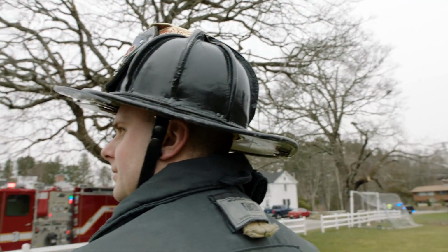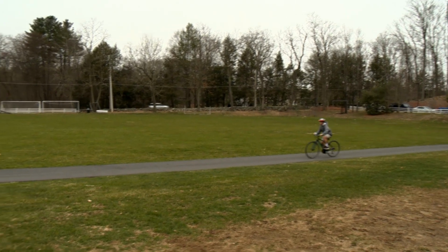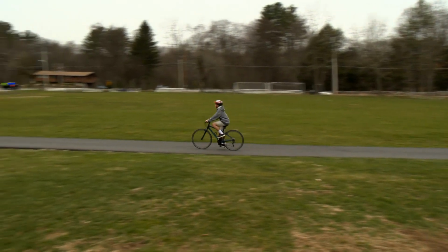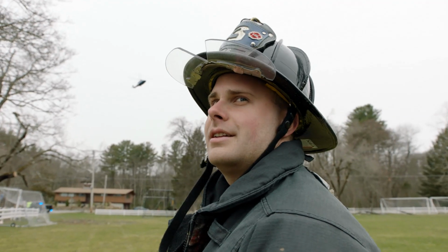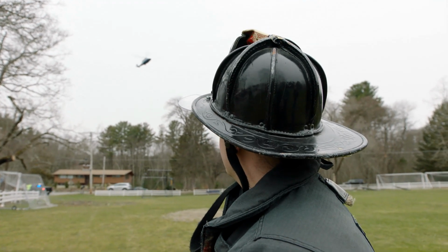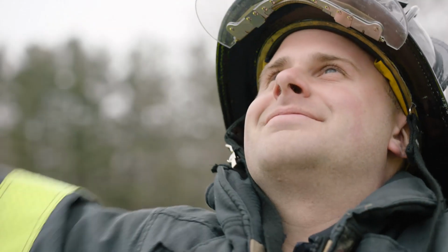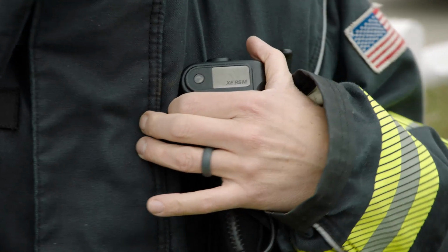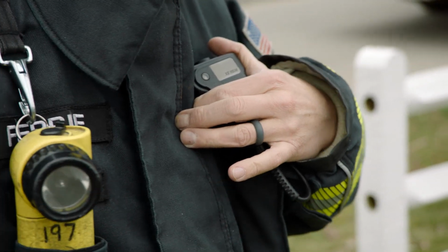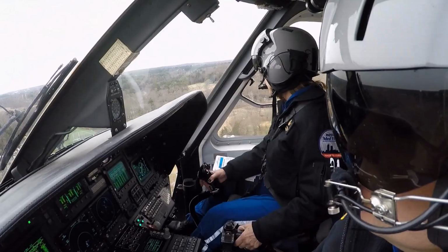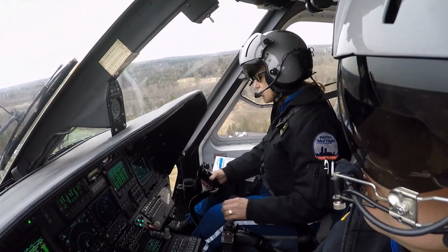If the LZ command sees a hazard in the LZ area, such as a person running or a car moving to the LZ, there are two simultaneous actions they must take. The LZ command must wave their hands over their head in the direction of the aircraft to alert the pilot of the hazard, while contacting the aircraft on fire department radio frequency, clearly stating, "Abort, abort, abort your landing."